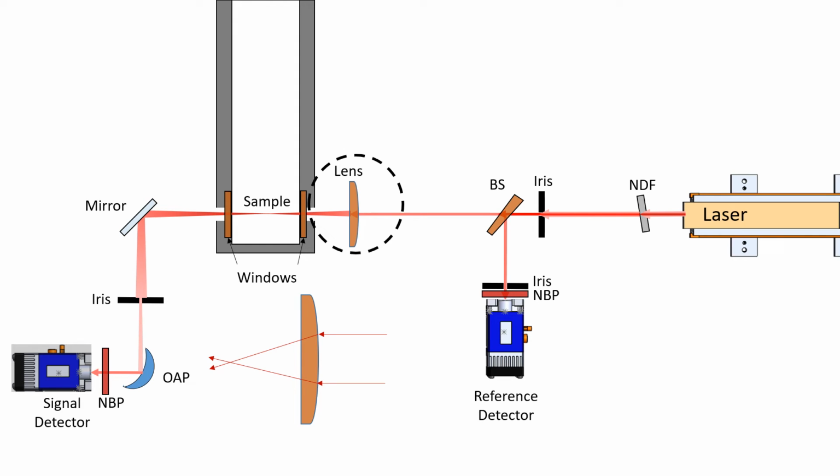We already saw a version of this in our upstream optics. A change in the refractive index from air to glass is the reason that the light is offset slightly as it passes through the NDF and beam splitter. A shock wave is essentially a very intense density gradient. Beam steering is most pronounced for large pressure gradients and non-homogeneous beam profiles, such as the Gaussian beam we're using here. Compressing the beam to a smaller diameter minimizes both of these effects.